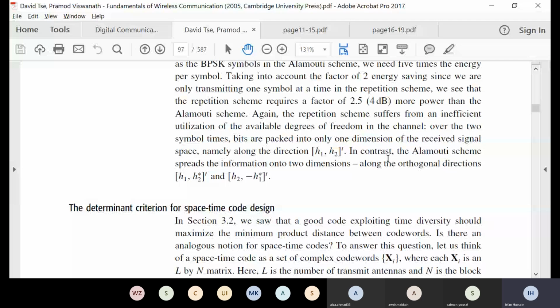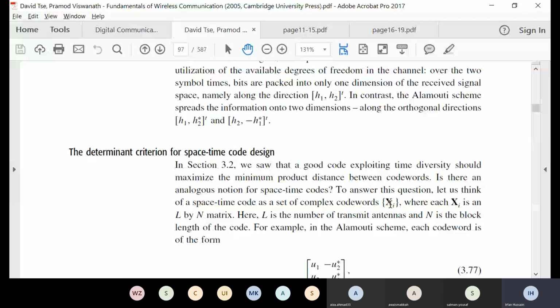Remember, when we were developing a codeword, for example, convolution code or linear block codes or rotational codes, if you could see, those codes were only in time, but you could repeat them through space, as in the case of rotational code or repetition code, where you were repeating your set of symbols. Here, we have to develop a code both in space and time.